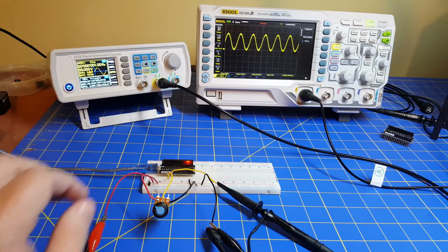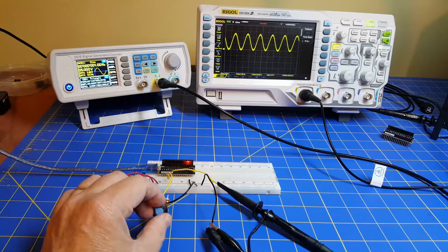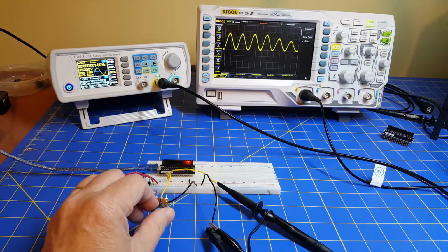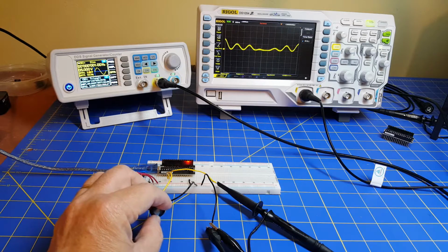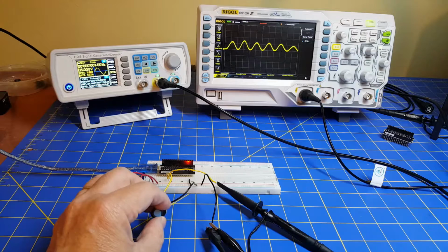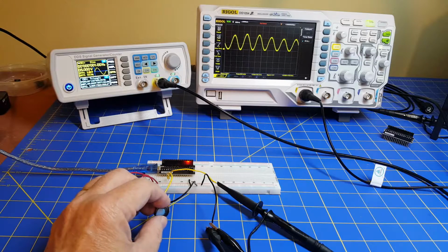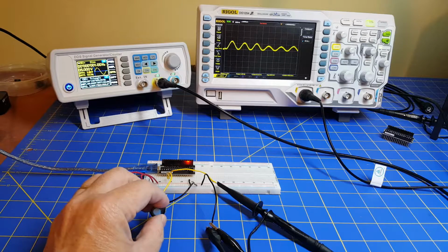Now, logging is for capturing very low frequency stuff like this, and as you can see, as I change the potentiometer, the magnitude of the waveform drops. So if you can imagine signals like mechanical signals or pressures or temperatures that change slowly over time, logging is what you would use to gather that data. And you might grab a sample every half second or every second or whatever, and then print it or plot it or put it into a CSV file or whatever.